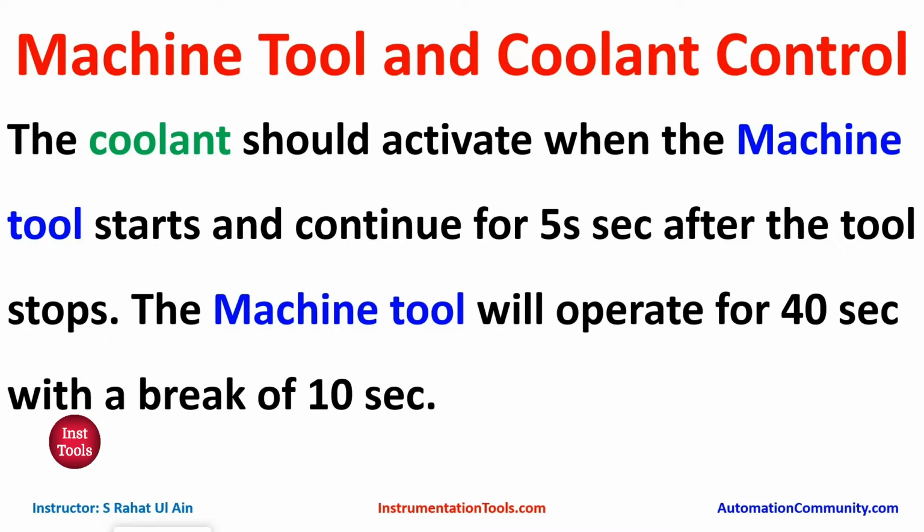So the coolant will operate for 45 seconds and then it will stop for 5 seconds and then again it will start for 45 seconds and again stop for 5 seconds and it will repeat this process again and again. So let's move to EcoStruxure Machine Expert where we'll draw a ladder diagram for machine tool and coolant control.